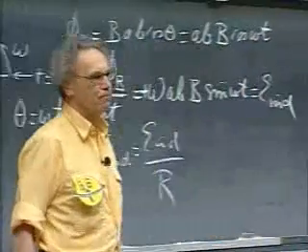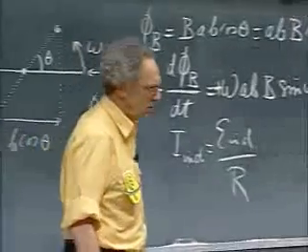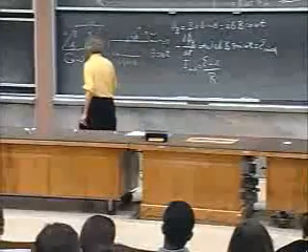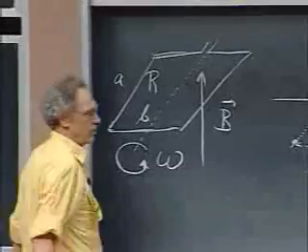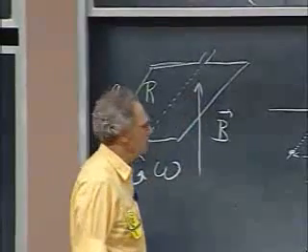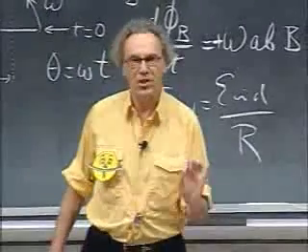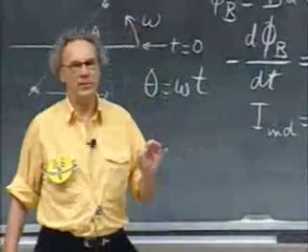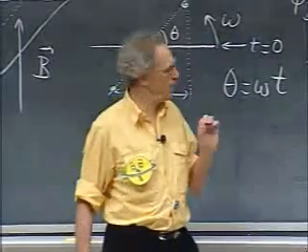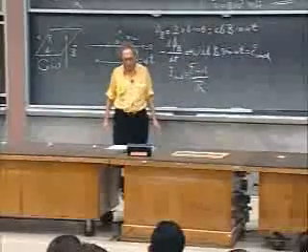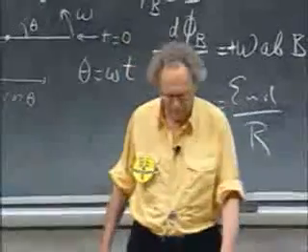You built motors, and during the prize ceremony, I told you that the faster your motor rotates, the larger the induced EMF that is generated in the loop. You had a magnetic field, which let's assume is more or less constant. Of course, it wasn't in your case, but let's assume so for the sake of argument. And as your motor rotates, there was an induced current generated by Mr. Faraday, which is proportional to omega. So the current is larger when your motor goes faster. And that induced current opposes the current which was produced by your battery.